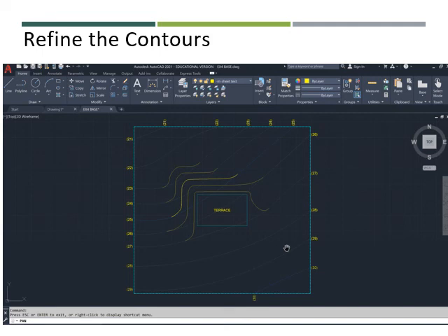We're simply showing you the process, and you're going to work this out on your own with our help and with the help of the TAs for the AutoCAD portions of it. So again, you're responsible for including the legend, the north arrow, the title block, all of the spot elevations, the proper text, the text that is then masked, all of the things that are required for a grading plan. If you have trouble remembering what's required for a grading plan, go back and look at the exercise where we're having you trace an existing grading plan, or simply ask us in class or ask the TAs.